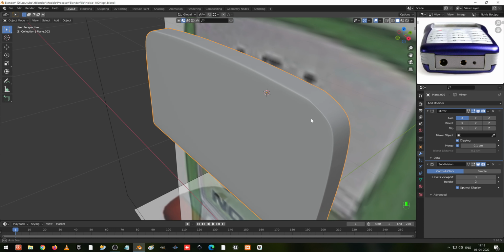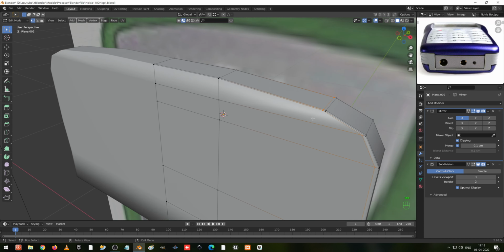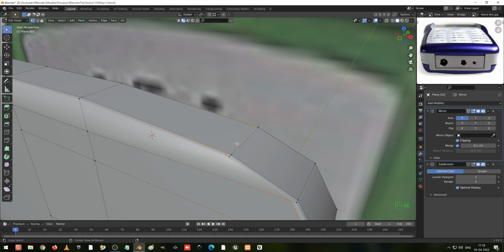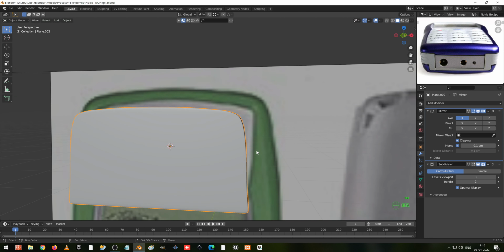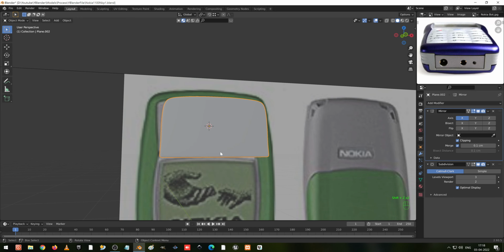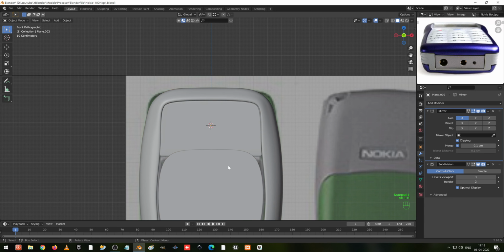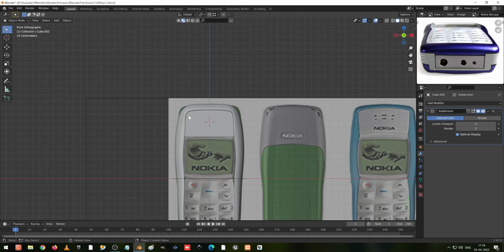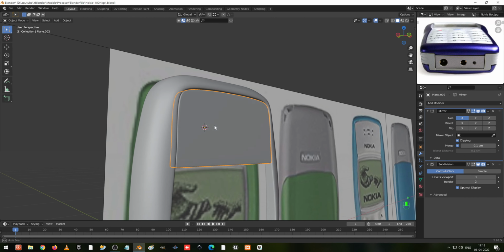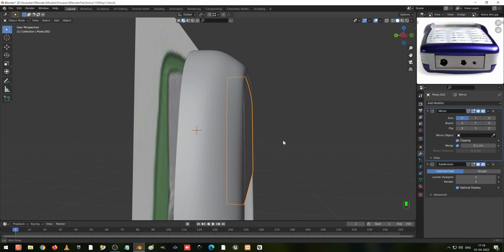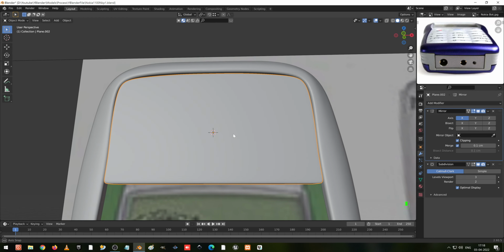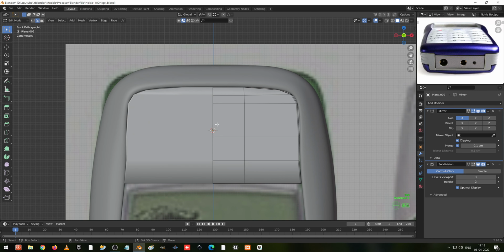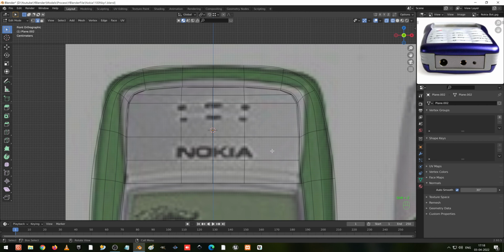Here right click and shade smooth. Due to this item it doesn't come perfect. Double G to move here. Now it's a better look. Go to the front view and Alt H to unhide, and I just hide these two now also, because we have not completed this design yet. Okay, fine. It looks better, I feel, than the auto smooth.